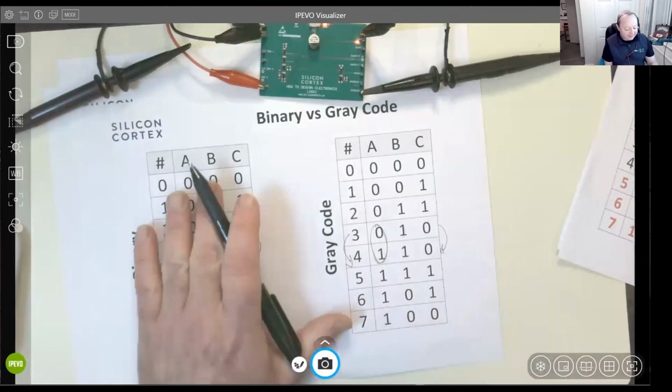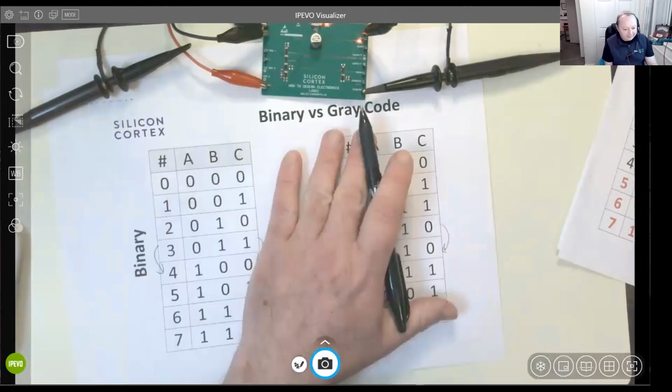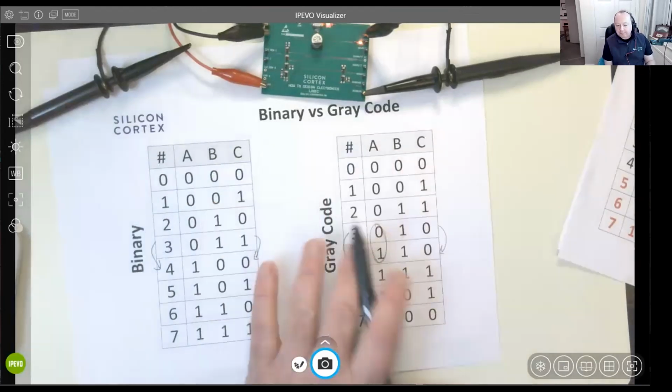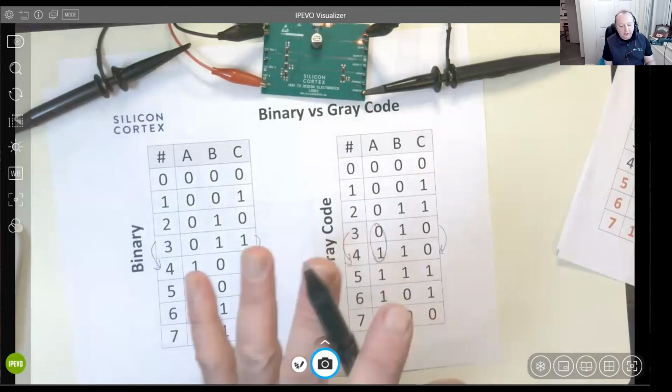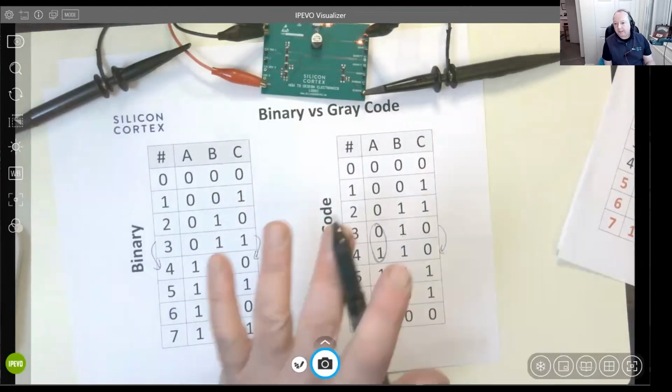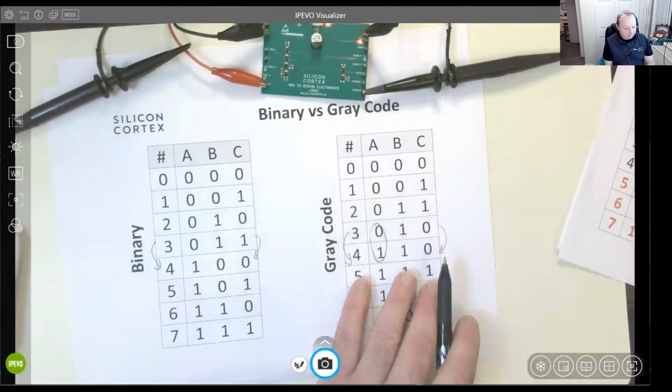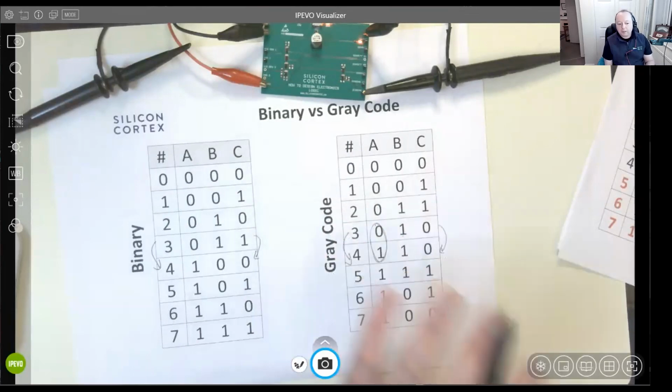So yeah, EMC is a nightmare. If you've got clocks going, or lots of logic edges going all the time, like they might in a memory system, for example, you can expect trouble, particularly if they're going all the time.